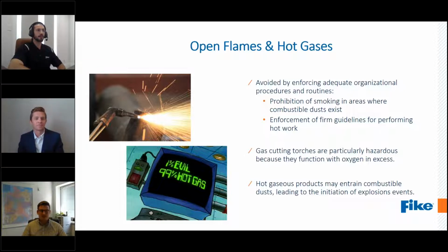We can avoid these by enforcing adequate organizational procedures and routines. Prohibition of smoking in areas where combustible dust exists is an example of that. We can also enforce firm guidelines for performing hot work. An example where this might become an issue is gas cutting torches.